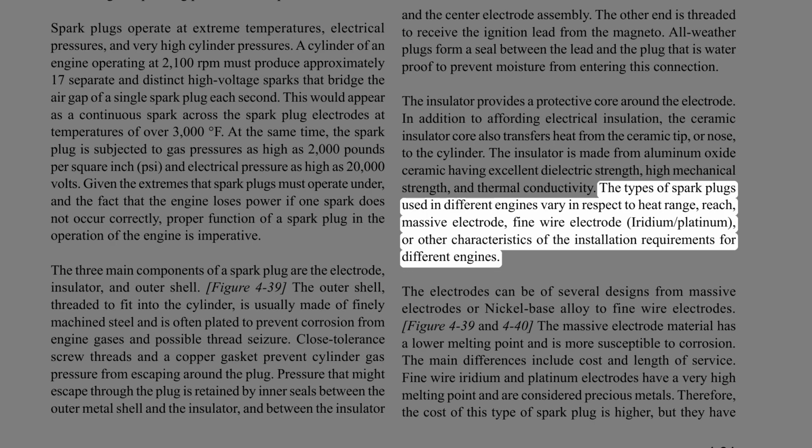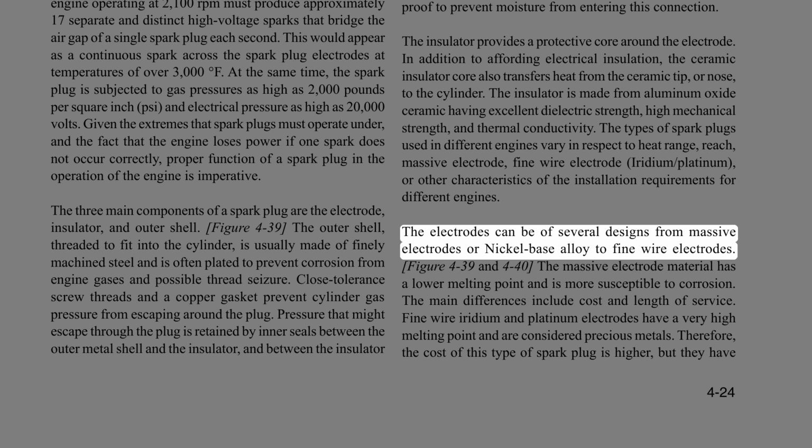The types of spark plugs used in different engines vary in respect to heat range, reach, massive electrode, fine wire electrode, iridium, platinum, or other characteristics of the installation requirements for different engines. The electrodes can be of several designs from massive electrodes or nickel-base alloy to fine wire electrodes.